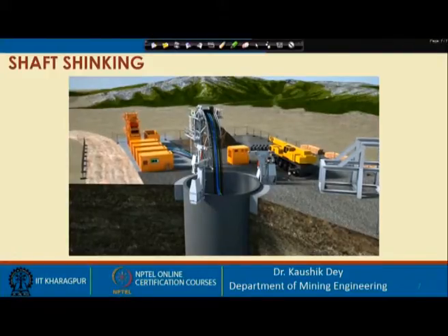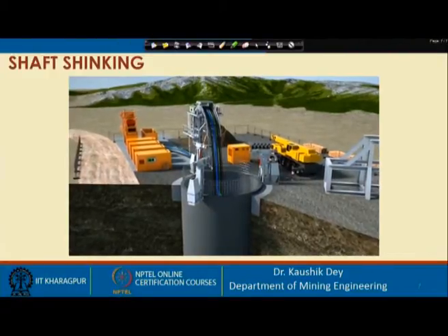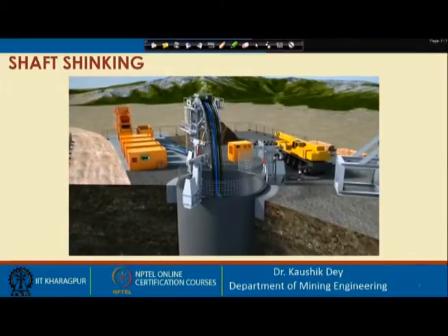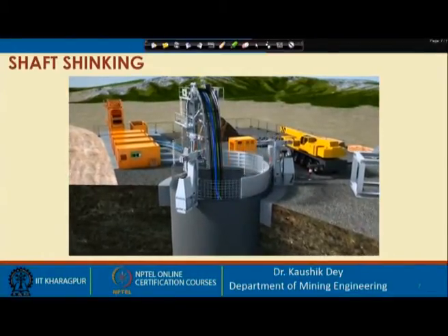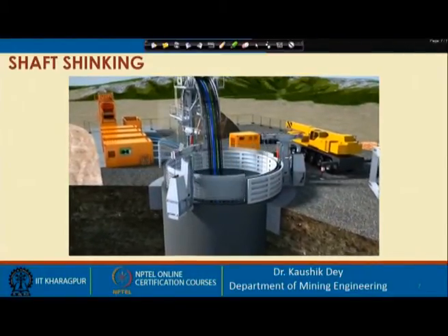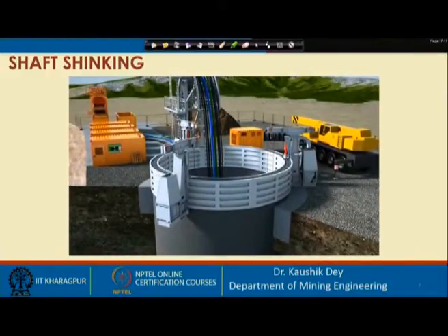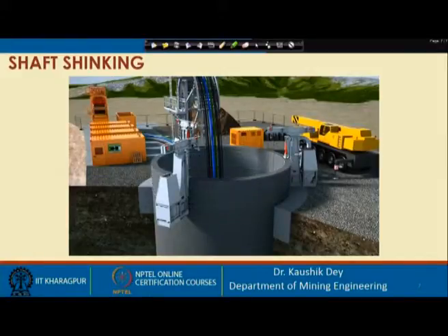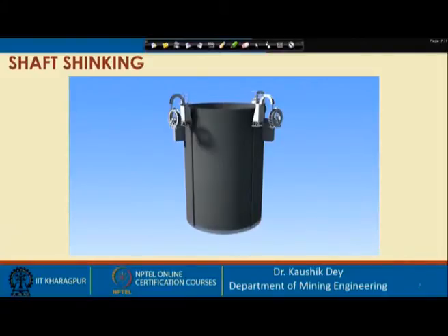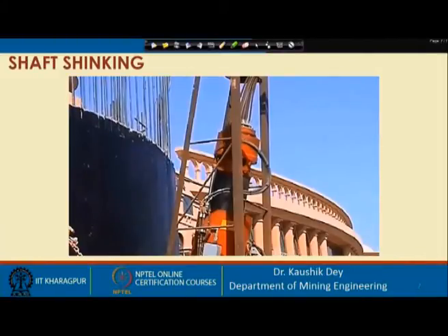As an alternative, the casing is completely lowered. So constructing the shaft from individual segment rings, in situ concrete can also be used. Formwork, designed for the shaft diameter, is used to concrete the shaft lining in lifts of about 2 meters in height. The sinking process itself is the same as for shafts constructed with segments.